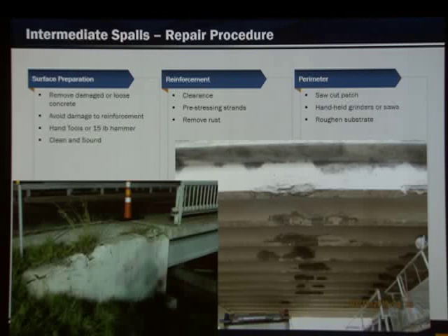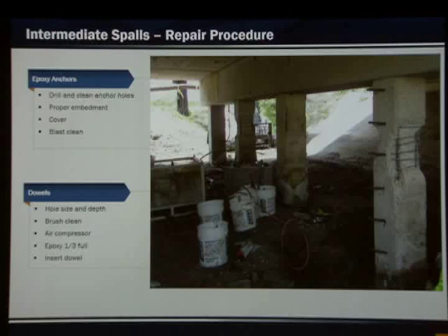And just be really careful if you're working with pre-stressing strands. You want to saw cut the patch to eliminate the feathered edges, and you want to use, again, handheld grinders or saws to square it up. And always roughen the substrate so you can improve the bond.